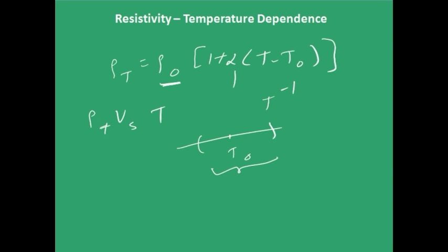You know that the formula for resistivity is 1 by sigma, where sigma is the conductivity. And you also know that conductivity can be expressed as n e squared tau by m. So I'll write this down, where m is the mass of electron, e is the basic unit of charge, 1.6 into 10 power minus 19, and n is the number of electrons per unit volume. Tau is the relaxation time, I mean the time between two consecutive collisions that takes place in the metal conductor or whatever it is. So when you increase the temperature, the electrons in the conductor move even faster, right?